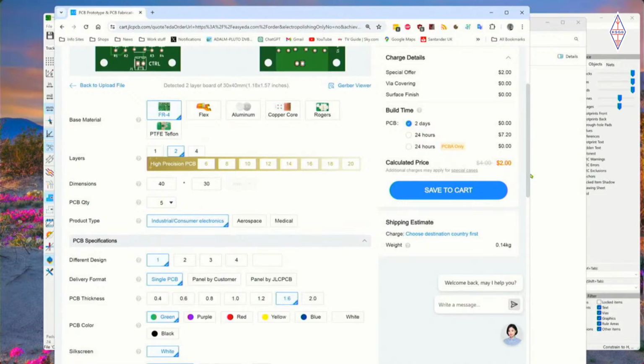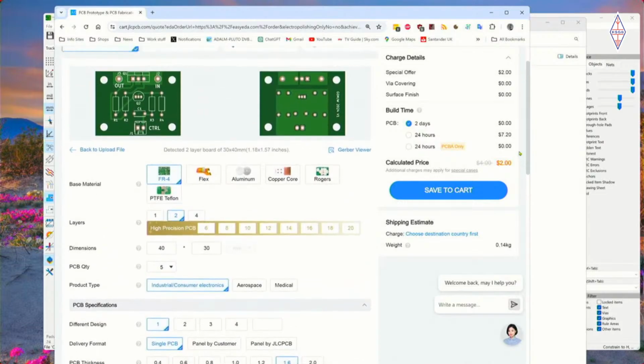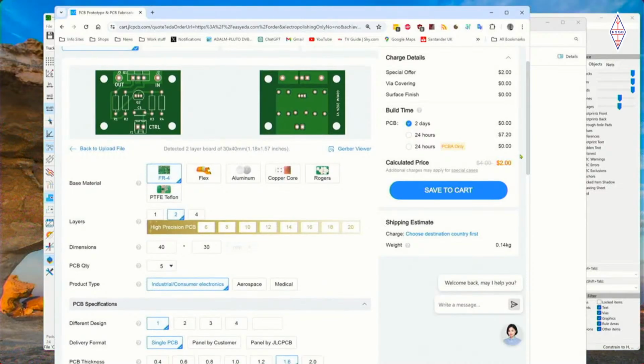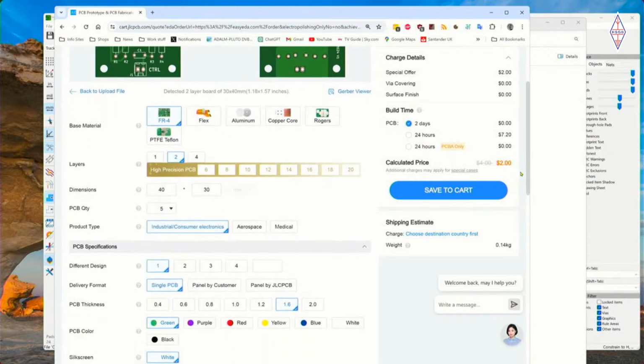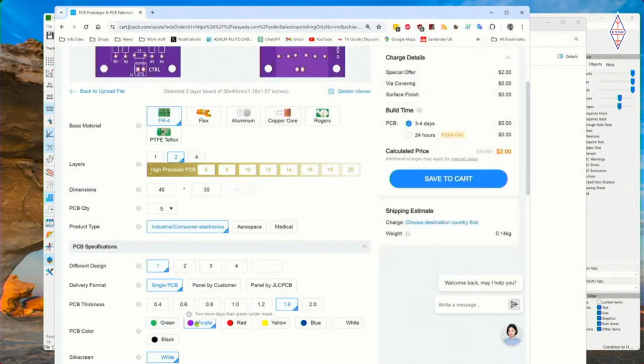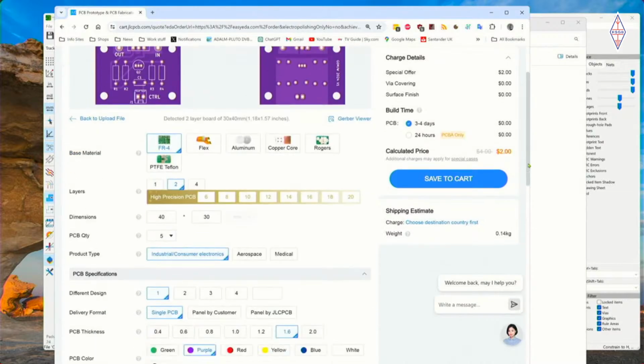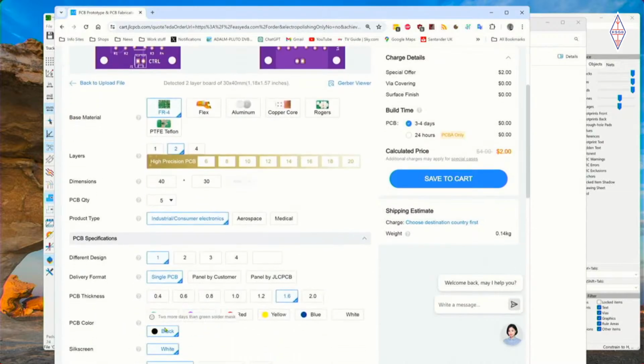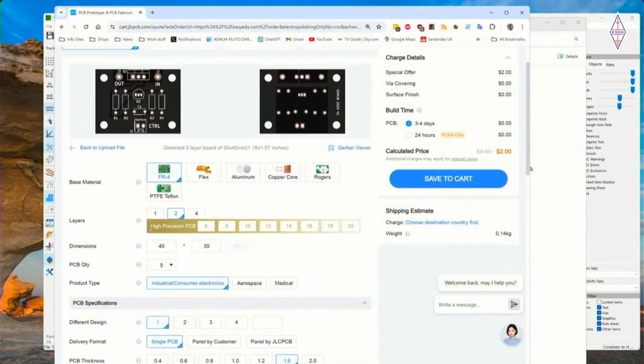No, and I was just going to come on to that actually, because what it does is it goes in between pads and stops you shorting them out when you solder it together. So it's very useful to have the resist. And you can choose different things. So you could have green, that's the standard, fastest turnaround. You could choose purple, but purple might take 3 or 4 days, and you see the board's now coming out in purple. Particularly nice is black, which is quite good if you use a PCB for a panel label, for example.